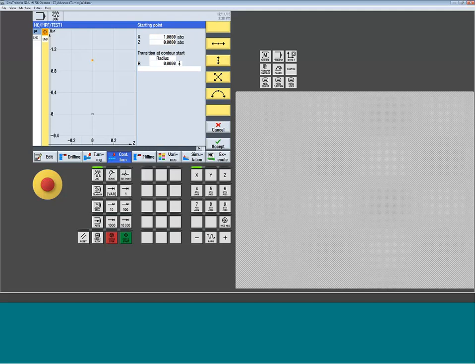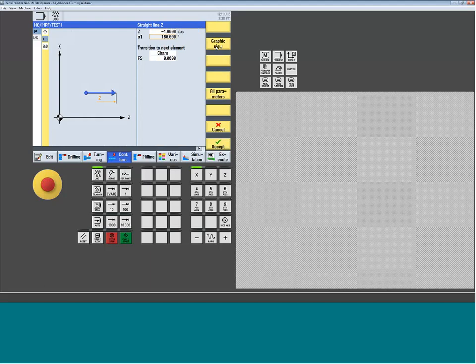So now, as we've done in all the previous examples, we're going to draw this shape. My first move is going to be a Z move back, and we're coming back to -1 inch. Once we get back, we're going to pull her straight out to a 2.5-inch diameter. So we'll give it the 2.5 inch. We do happen to have a chamfer here of 125, and we want to accept it.